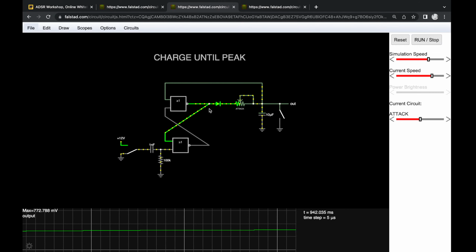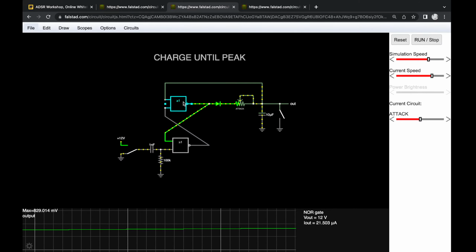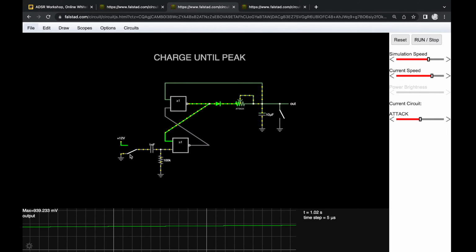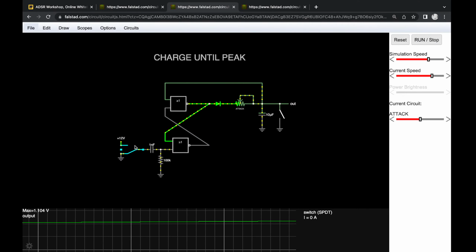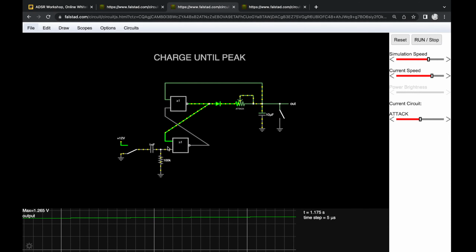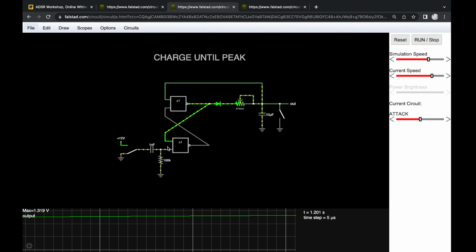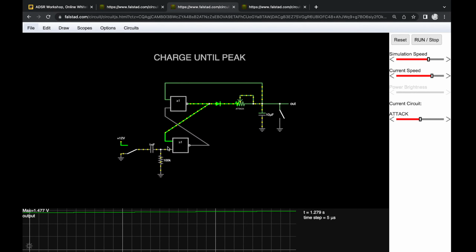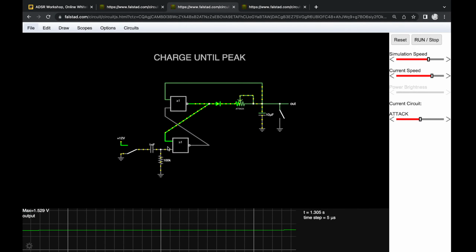So we need a way to make this flip-flop turn off whenever the key goes down or up, however you want to see it. So that's what we need. We need a second mechanism that resets the flip-flop whenever the key goes up. And now to do this, we could work with this simple SR flip-flop. We could keep working with this. But I've actually found an easier way to implement this with a little bit more complicated type of flip-flop. And that type of flip-flop is called a D flip-flop.